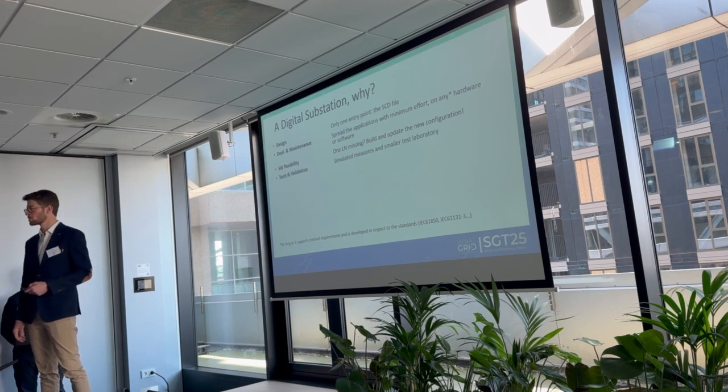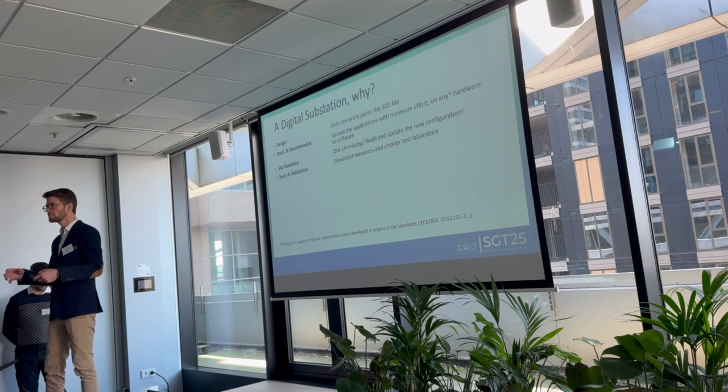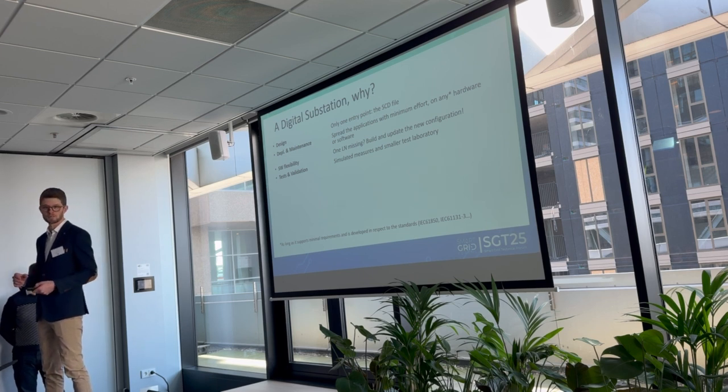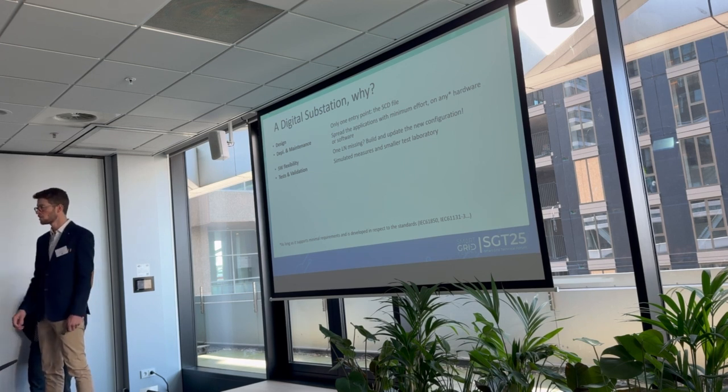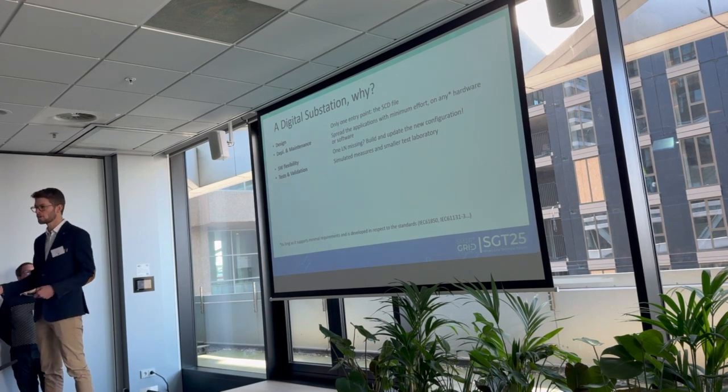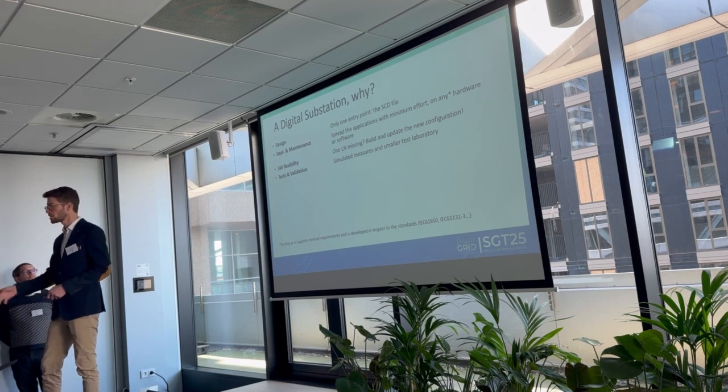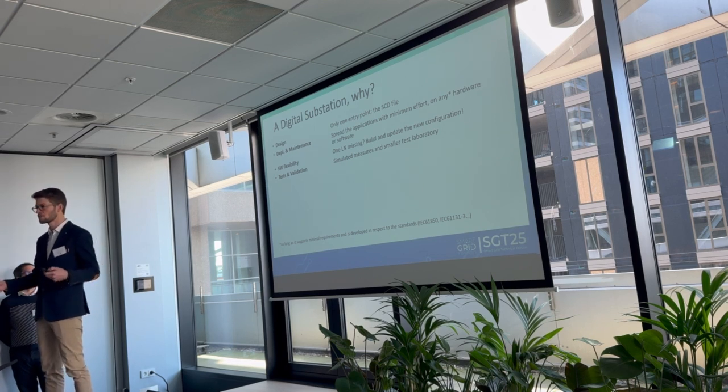If it's digital, you can simulate it in a smaller cabinet, because you don't need to have a lot of real devices that will send sample values, that will send some GOOSE messages. You just create virtual IEDs, and then you can validate theoretically that the control center is doing the right stuff.